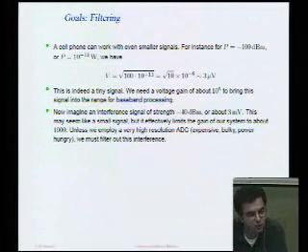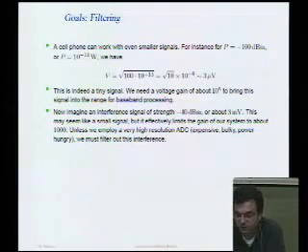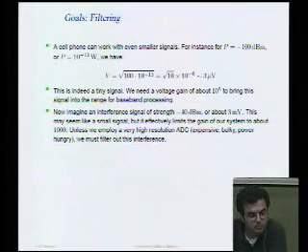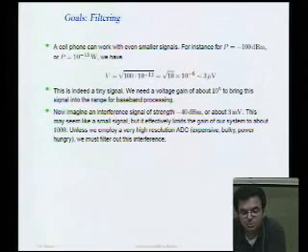Start out with, let's say, 100 millivolts, and then keep making the voltage smaller and smaller. And as you get into the microvolt range, you'll see that it's all blurred out, it's all noisy. That's because of the finite dynamic range of that oscilloscope. And it's also because of the noise that's present with that signal.